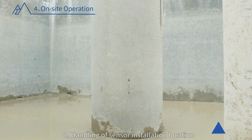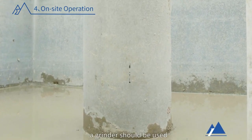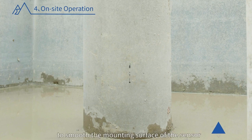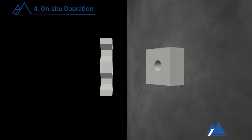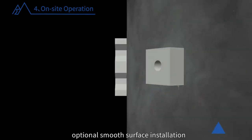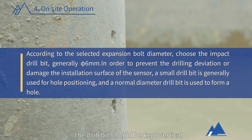4. Handling of sensor installation location. For cast-in-place piles, the grinder should be used to smooth the mounting surface of the sensor, and the mounting surface of the sensor should be parallel to the axis of the pile. For pre-cast piles, a smooth surface can be chosen for installation. 5. When drilling, the drill bit should be kept vertical to the side surface of the pile.